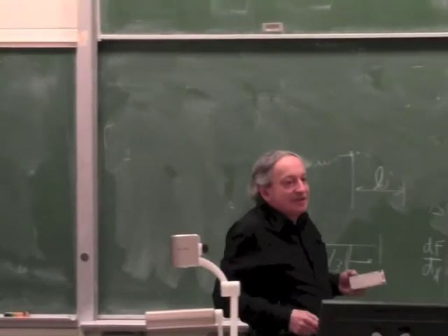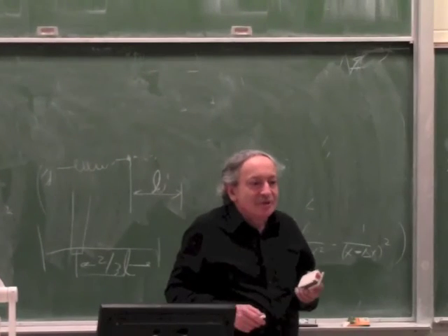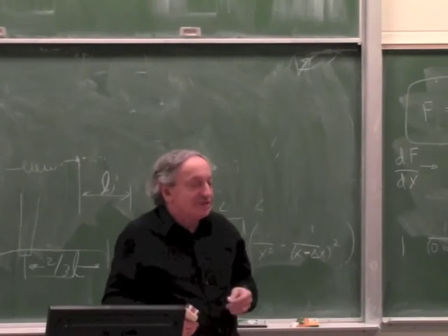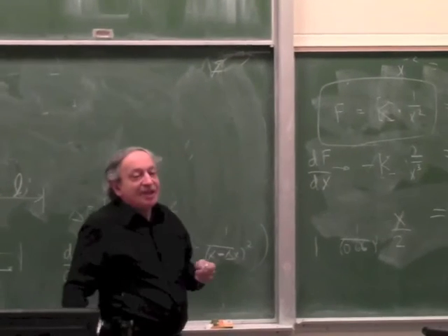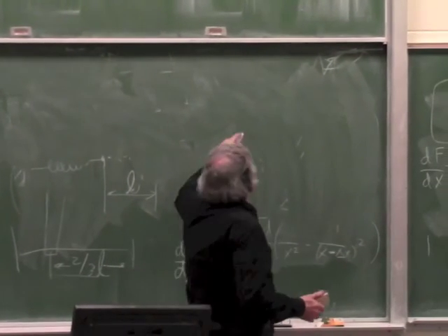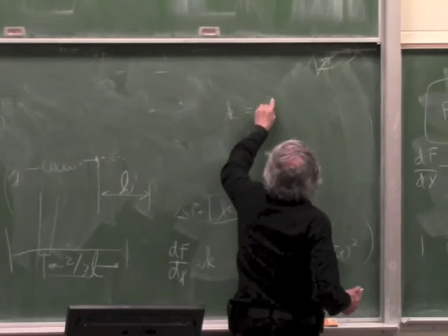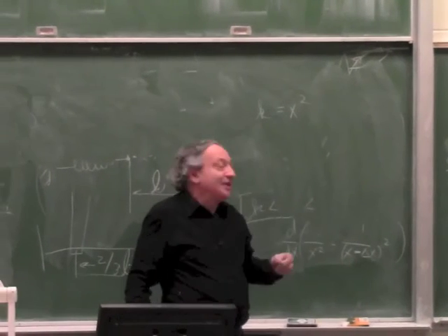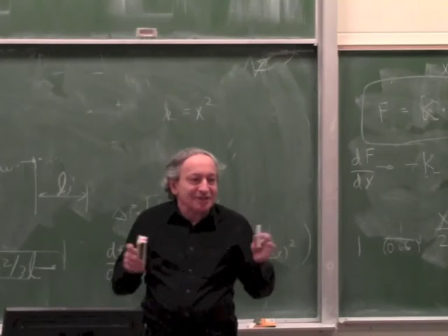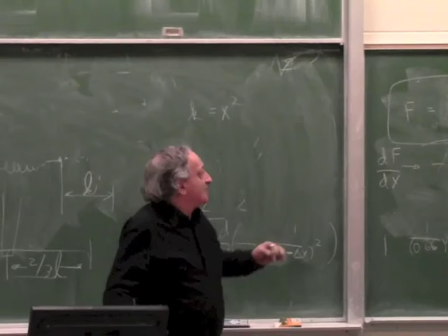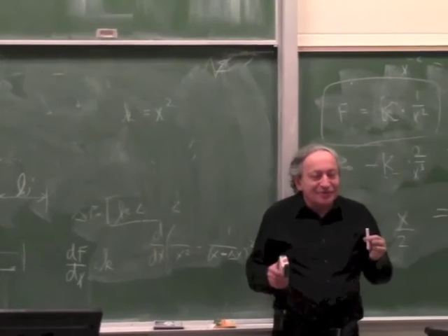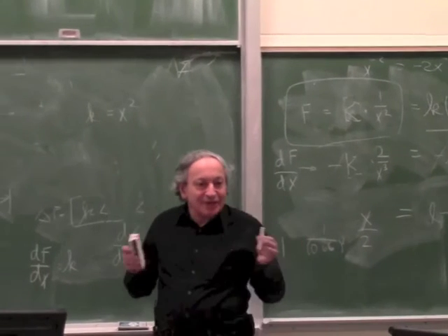Have they tried using nonlinear springs? What is the effect of that? A nonlinear spring? Yes, that's a very good idea. Excellent suggestion. Another solution is to take a nonlinear spring which will have the same x squared behavior. It's very easy to make a spring which is k equal x squared. If you match a nonlinear spring with a nonlinear actuator, then you have a much, much better range. But it's still not perfect, because this is only a model which doesn't take into account saturation. So it will still do funny things, but it will have a wide range.